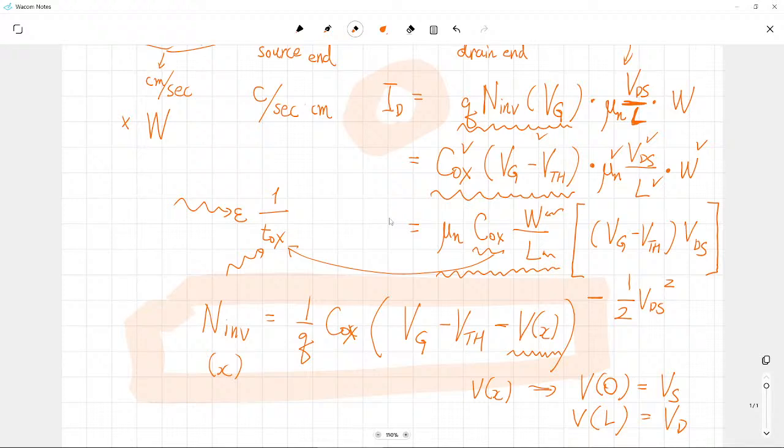It is because our channel is also reacting to the drain voltage. So if we apply a higher drain bias voltage, what will happen? Our electrons collected in this channel region are strongly accelerated.